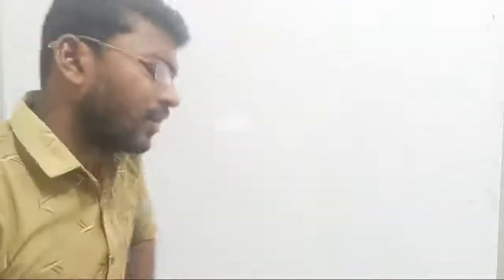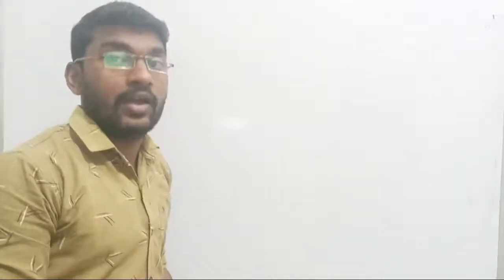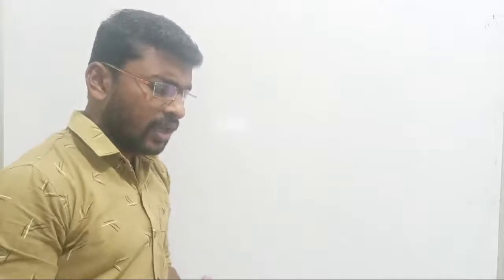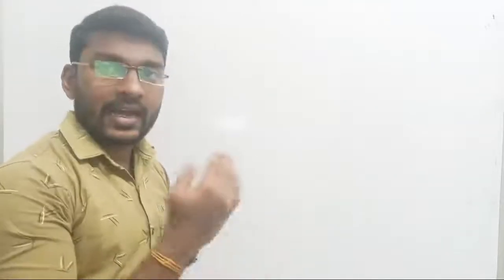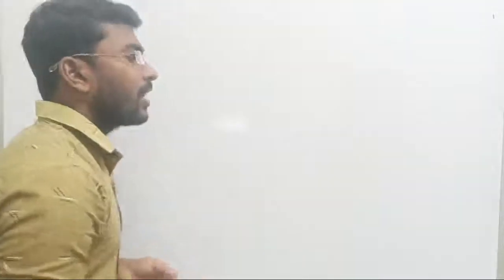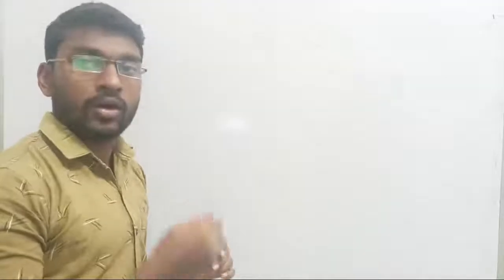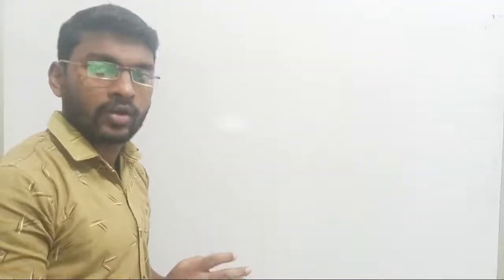Suddenly some of you got the doubt, and some of you asked the doubt in our group also. I have seen it, right? I replied that I will tell you the answer later on. Today is the last lecture, so I am going to conclude all those things. So the thing is, why? First I will start from the alternator once again and classify the faults, and let us see how we are going to calculate the effect of line to ground fault, double line fault, triple line fault, triple line to ground fault. Everything we are going to see now, right?